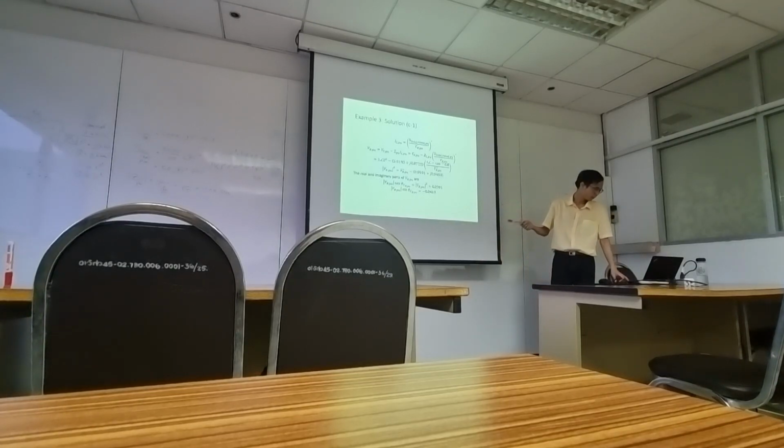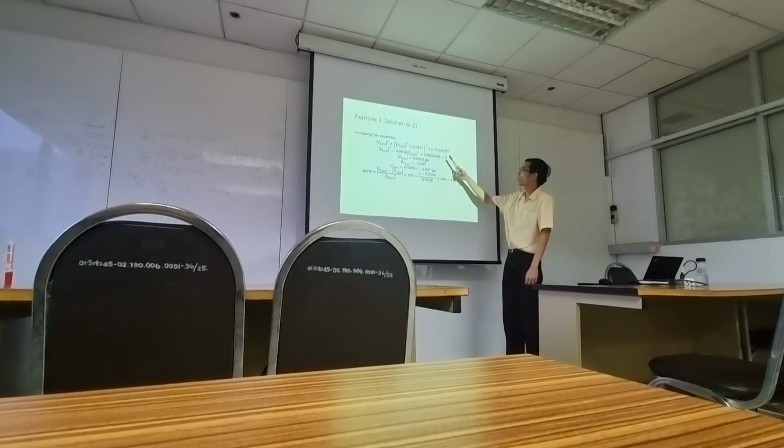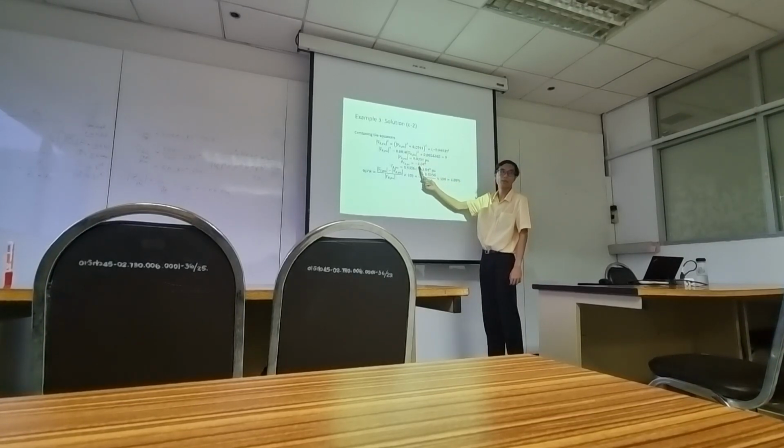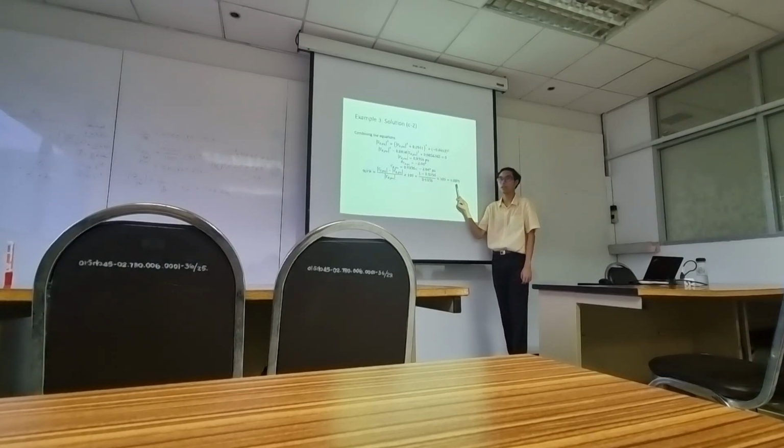Then try to solve this equation. Combine the equations, try to solve it. You will get the magnitude and also the angle of VR. This is magnitude and this is angle. Calculate the voltage regulation, do the same thing. 6.8%.